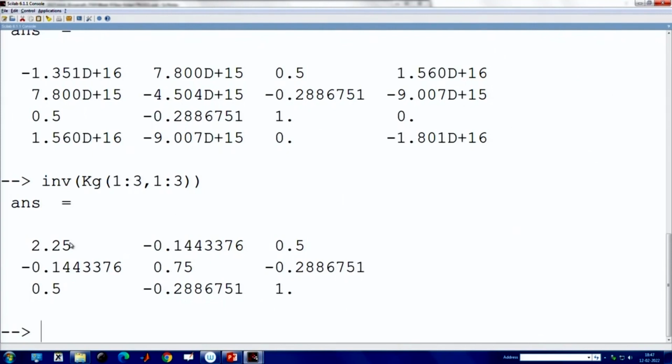Here also we observe the same thing. If we do not provide 3 constraints, then the final stiffness matrix we use for the solution is unstable. So, this is very important. Whatever you observe in the solution, if your model is right, if your idealization is correct, if your equation closely represents the physical phenomena, then what you observe in the solution is a manifestation of some physical process.